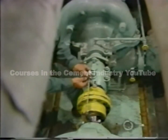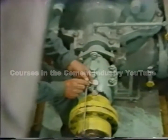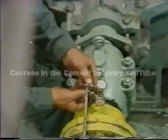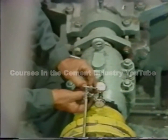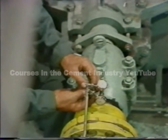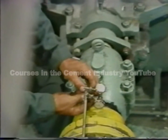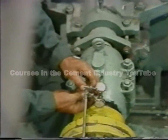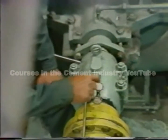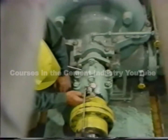Once the first dial is securely mounted against the face of the post, the second dial indicator can be mounted on the top of the post to indicate parallel misalignments. The dial should be resting securely on the post and be snug so that no unwanted movement occurs. Gentle tapping on both dials and the rod will indicate whether or not the fittings are rigid enough.